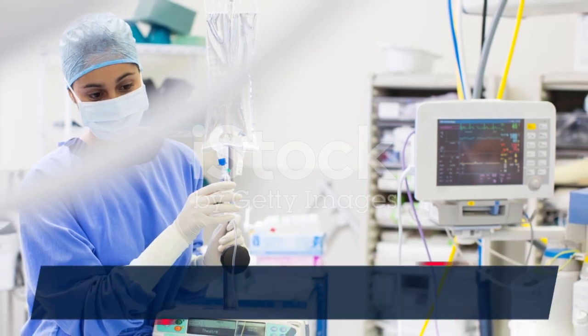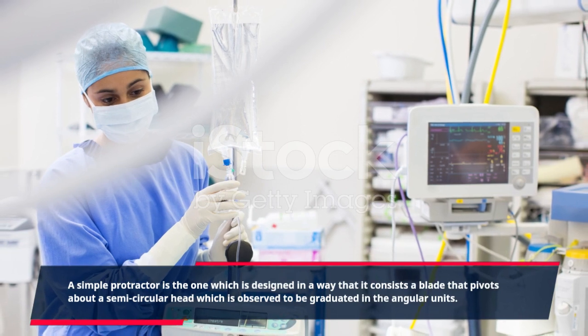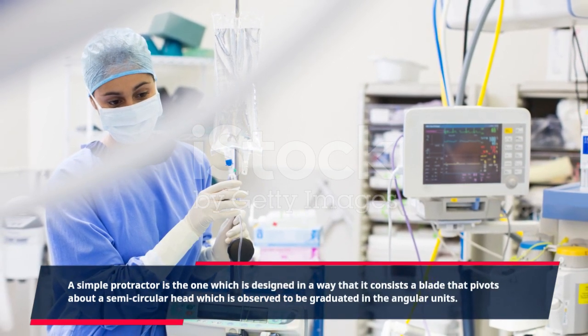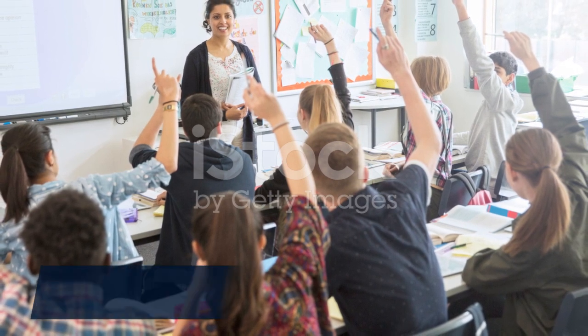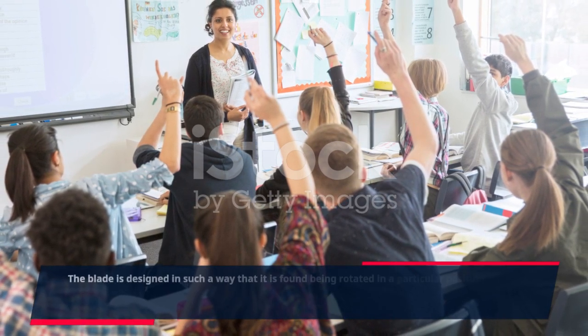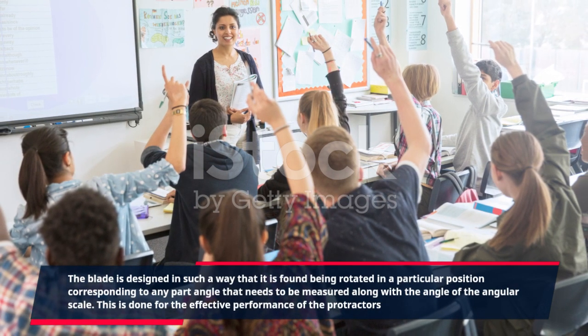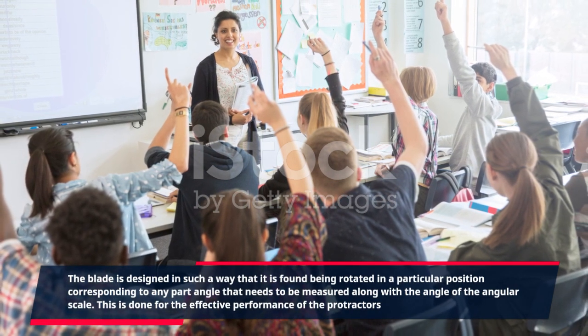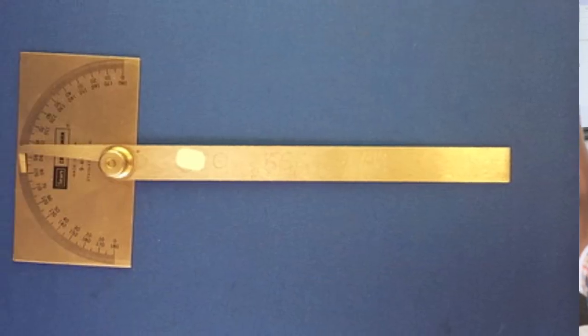A simple protractor is designed in a way that it consists of a blade that pivots about a semicircular head which is graduated in angular units. The blade is designed in such a way that it can be rotated to a particular position corresponding to the angle that needs to be measured along with the angular scale. This is done for the effective performance of the protractors.